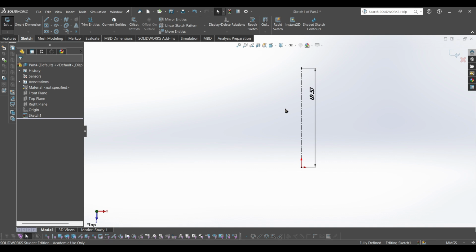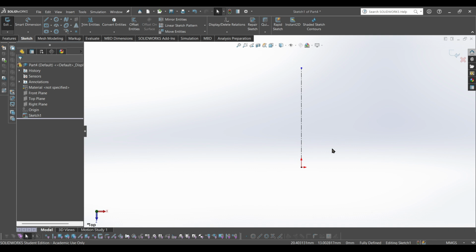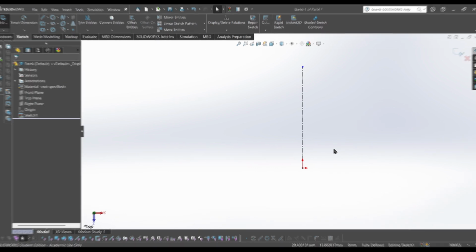But the main difference between normal lines and center lines is that center lines are not used to actually make sketches. They're used to help create references for your sketches, or guides as you're making sketches, or help you visualize as you're making sketches. And the most important, and in my opinion the most helpful thing about center lines is you can consider them as lines that don't count when you're trying to use features. And I'll show you exactly what that means.